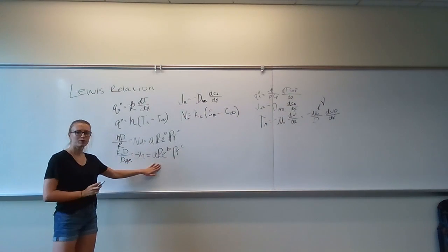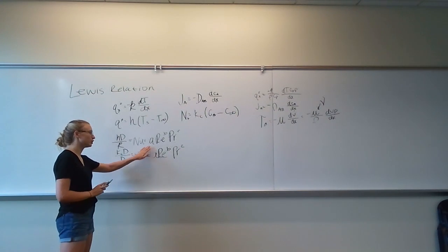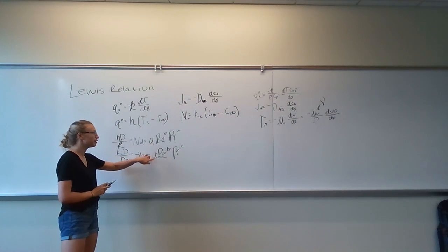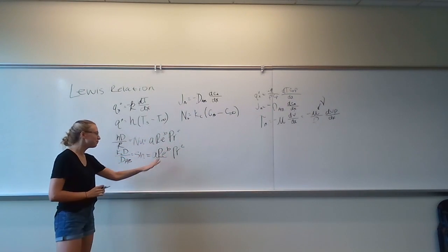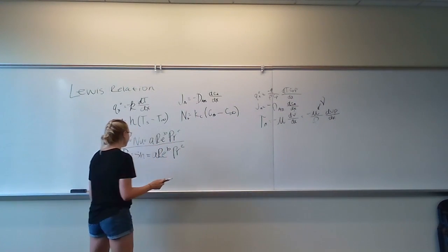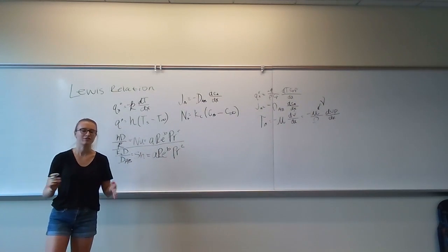So through experimental data, we find that all of these coefficients for both the Nusselt and the Sherwood number are the same. So A is the same for both the Nusselt and Sherwood number, B is the same, C is the same. So we can divide these two equations and relate the Nusselt and the Sherwood number to get a mass and heat transfer relationship.